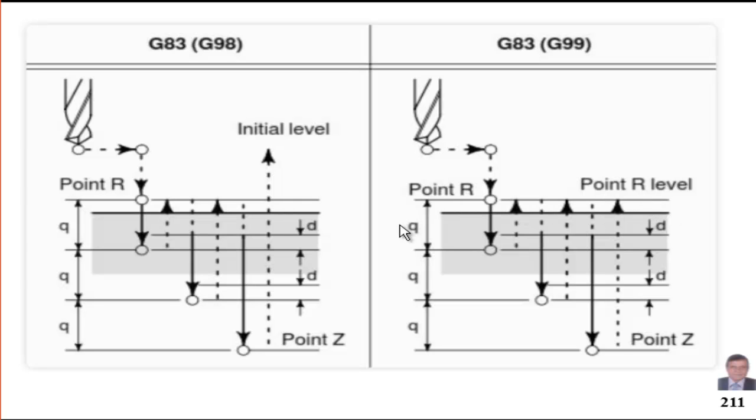As you see again, this solid line indicates feed movement, and this dotted line means fast movement. So as you see here, the cycle by itself will be done like this. The feed movement will start a little bit before the actual peck depth. It is to allow a steady starting of the cutting tool to do that process.